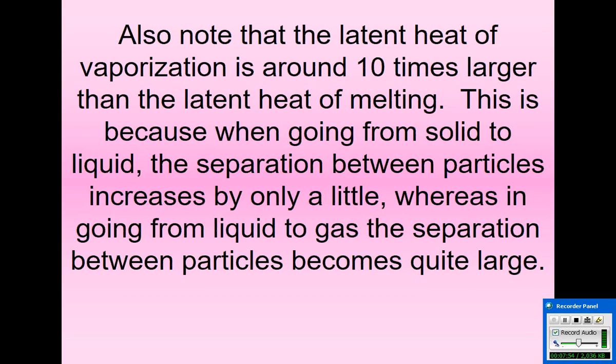We have to get these atoms and molecules separated from each other. So this attraction that keeps them close together in solid or liquid form, we have to break apart. So it requires a lot more energy. We have to do a lot more work to pull them apart, and that work manifests itself as a larger latent heat of vaporization.